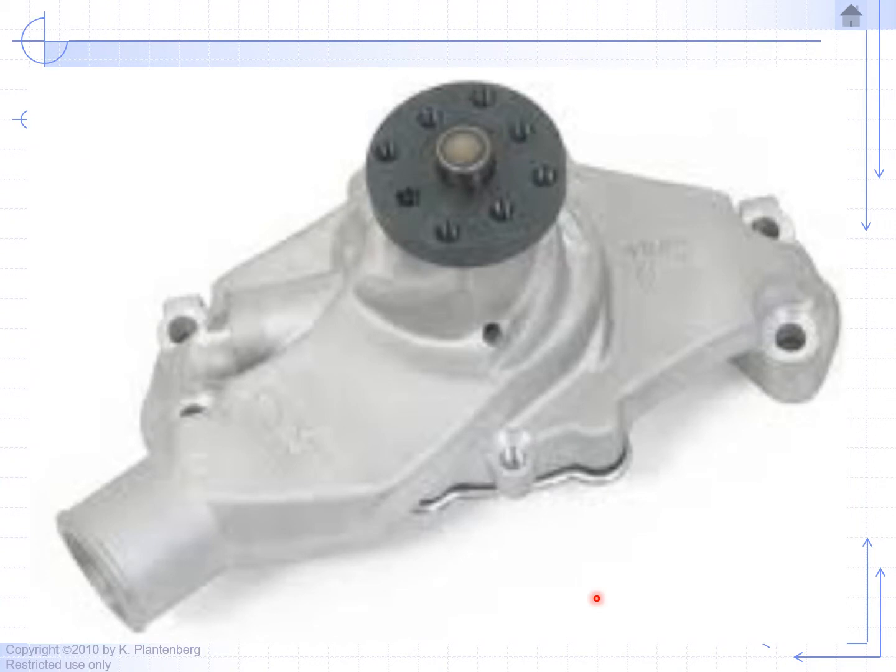Next slide. So here we have a water pump, an aluminum water pump for an old Chevy big block. So when it comes to water pumps like this, instead of having to machine this from scratch from a block of aluminum, it's easier if you pour it into a mold. So this would be casting. And when you pull it out of the mold, you're going to have a rough surface, which comes from the mold after hundreds and thousands of parts have been made. You'll have a rough surface on the mold. And once you come up with a rough shape from the mold, then you can go ahead and do some machining.